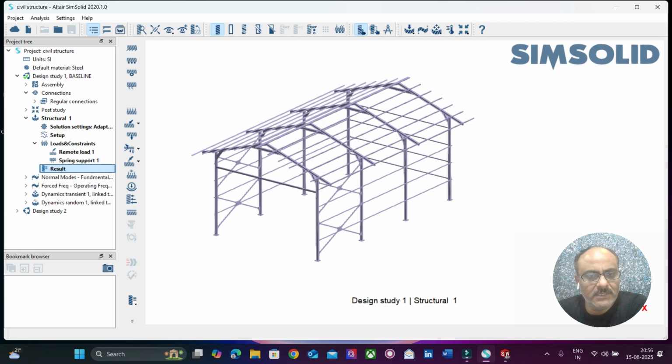So we know that the members are all steel, and the steel has a certain material property, based on which the initial loading conditions are taken. So we are considering two design phases. In the first design phase, we don't have any plate members. The roof is completely detached, removed, and then the simulation is performed on the skeletal structure.